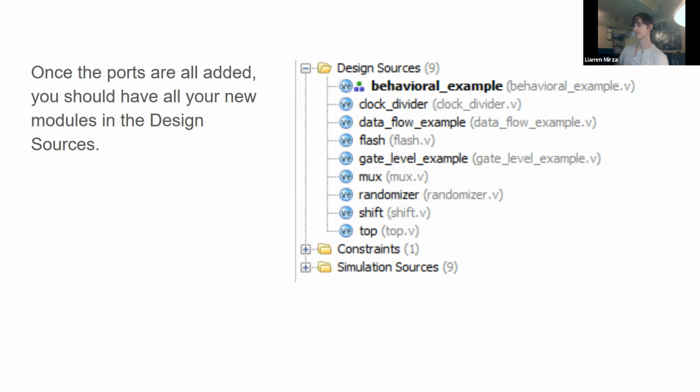And I guess for this one, you should set your top as your top module now, right, Gabe? Yep, that'd be a good idea. There's no code in it yet, but it'd be good to do that in advance. You just right-click on this one, set as top, and whatever was on before will switch to it. It just makes sense to make the top module the top module.